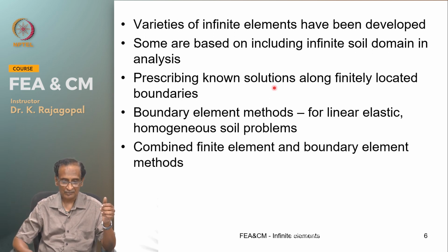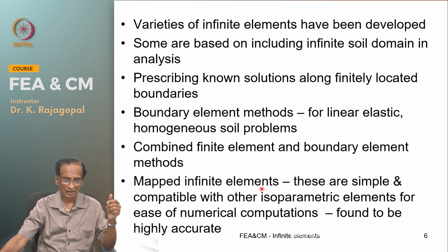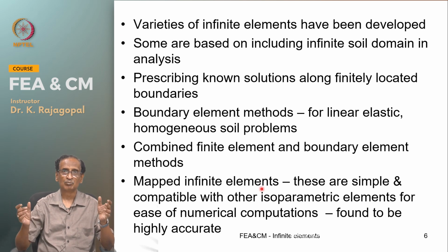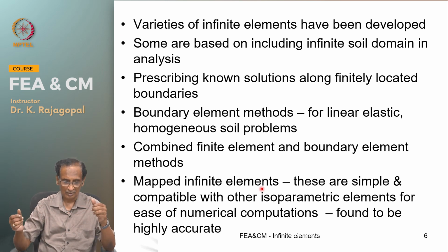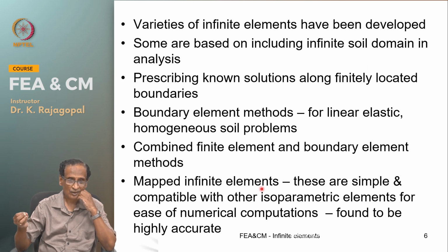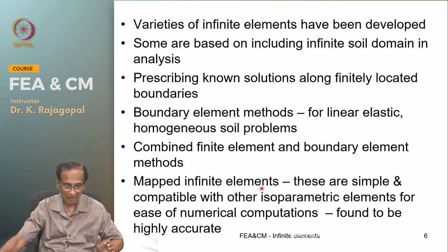And then the more recent mapped type infinite elements. These elements are very simple, and they are also isoparametric, so they are compatible with the other finite elements that we have developed. So, they are easy to implement, and we do not need to make many changes in the existing computer programs to implement these mapped type infinite elements.